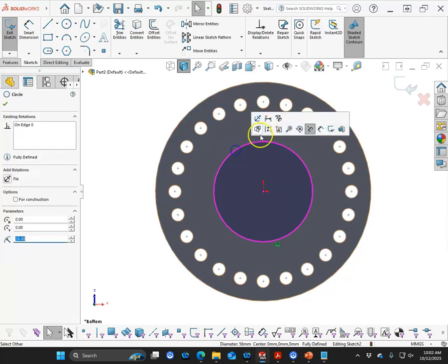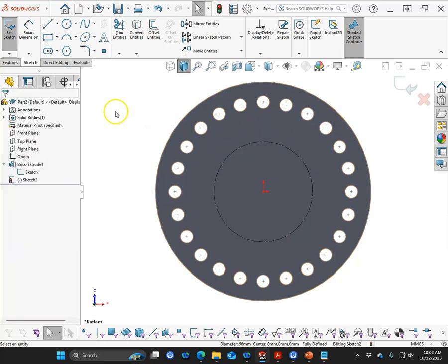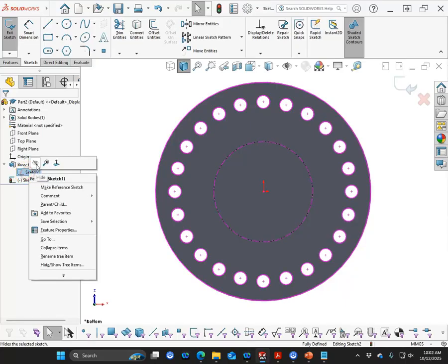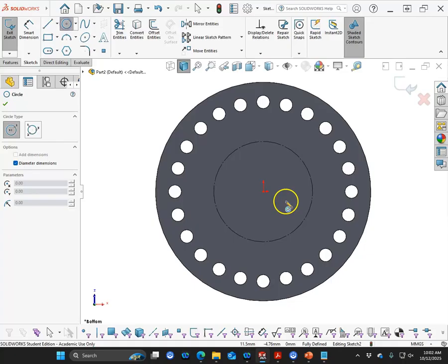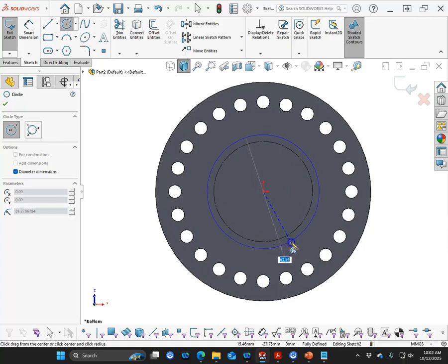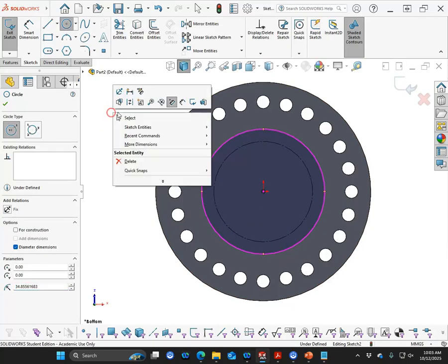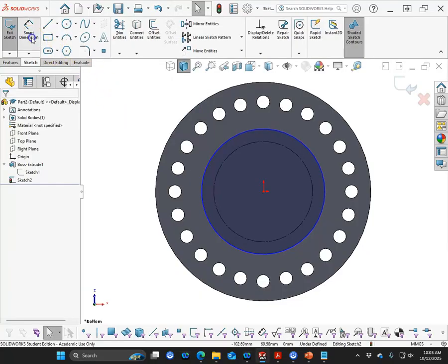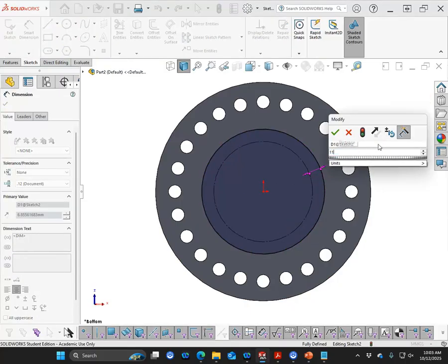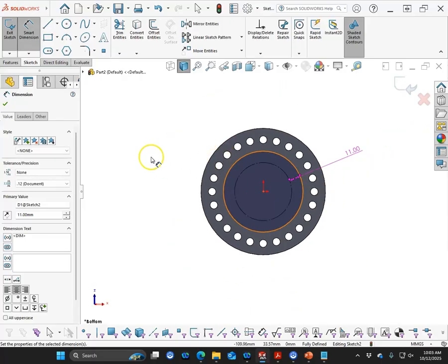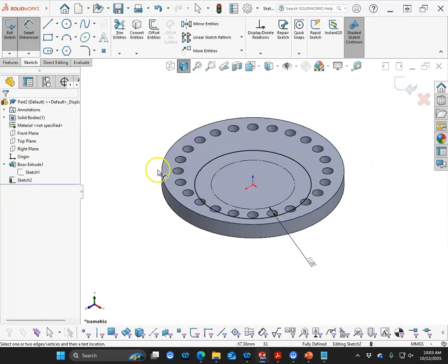And then I will switch it to the center circle because I want to keep that same geometry. If this changes, then it will follow it through. And then between the two circles, we're going to select, and that is also going to have the wall thickness of 11.